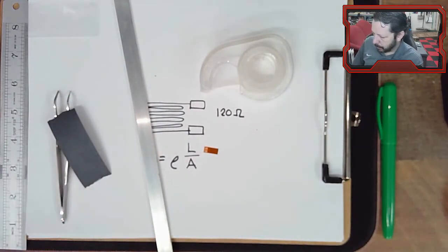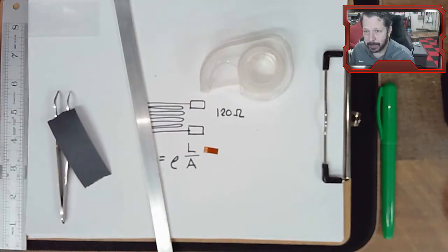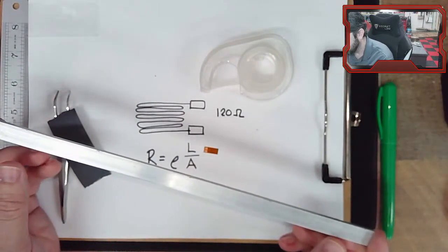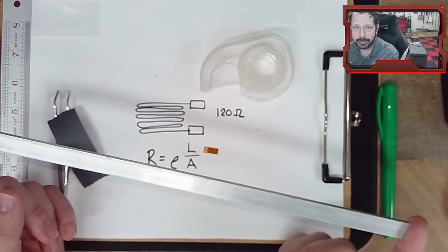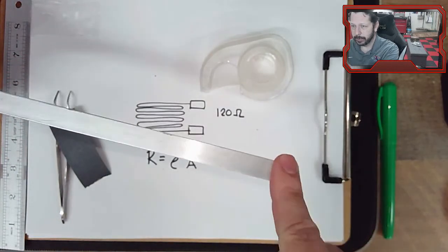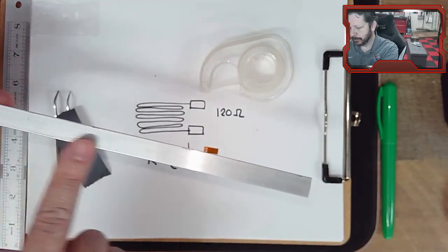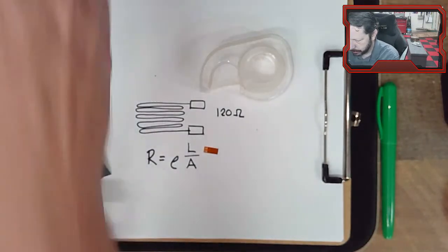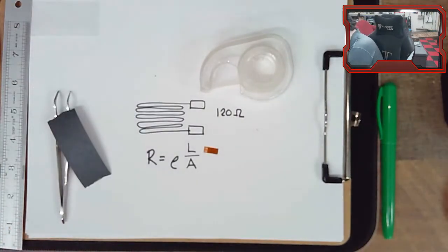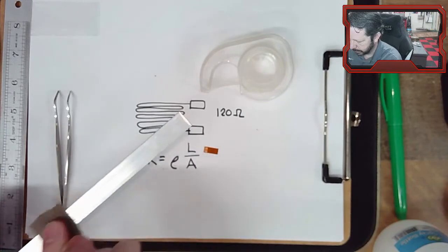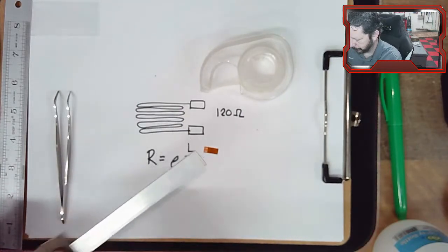So I'm going to clean up a spot somewhere near the center of our beam. It doesn't have to be the exact center. The beam we're going to build is basically a cantilever load cell. So it'll be held somewhere, and the force will be put over on the other end, and then we'll measure the strain on the top of the beam. So I'm going to pick a spot somewhere in here, put a little bit of IPA on there and just sand back and forth to get some of the oxidation off of it.